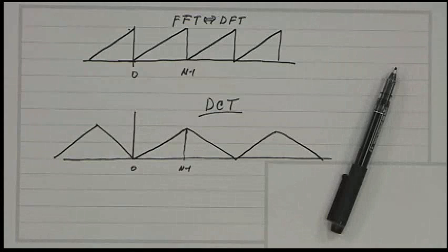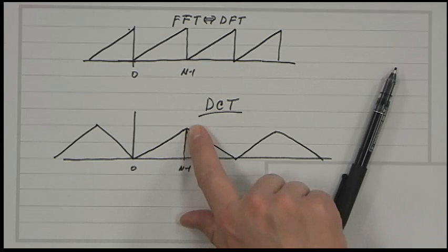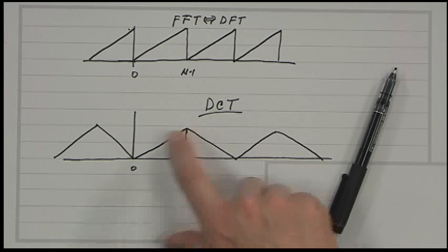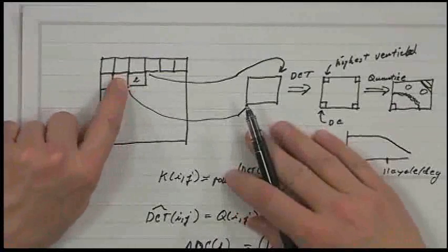Yeah? DCT also assumes that the signal is reflected. It assumes that it's reflected. So what artifacts might it cause because of this assumption? Well, you're still going to have a discontinuous derivative. So a larger block size is still advantageous, because there's always some loss of coding efficiency at the boundary of the block. And in general, you'll get blocking artifacts also because you're ignoring the redundancy.